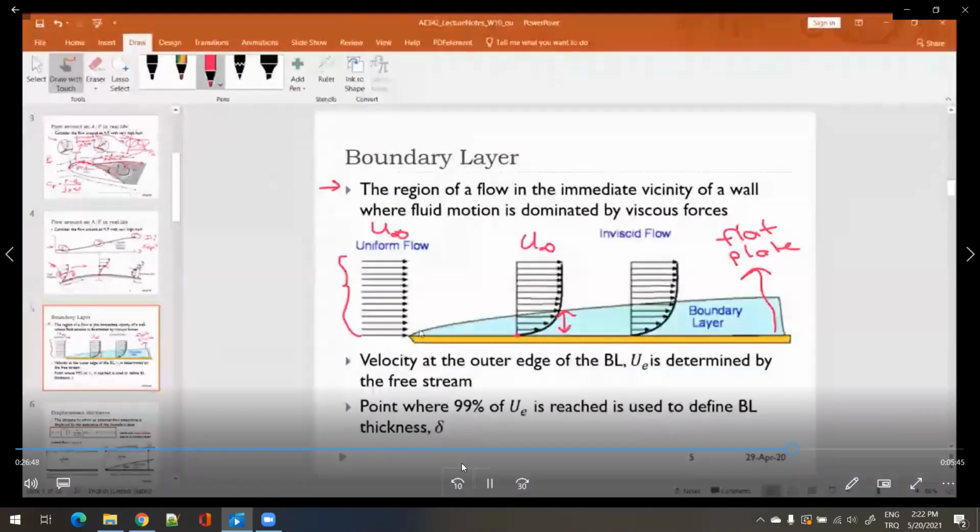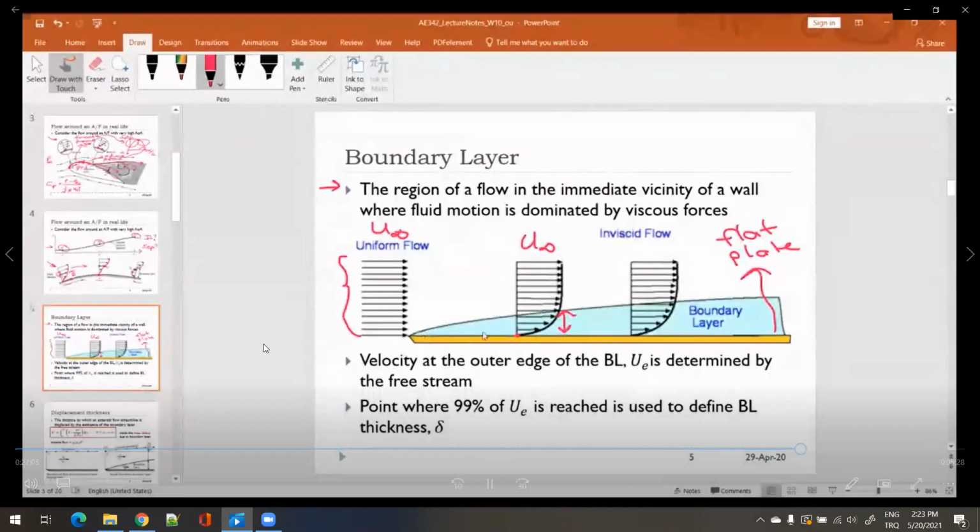The thing is, as the fluid particles move downstream, more and more momentum loss will start building up. Initially the amount of fluid particles that are in contact with the body is not much. They will keep losing and losing the momentum as they go in the streamwise direction.